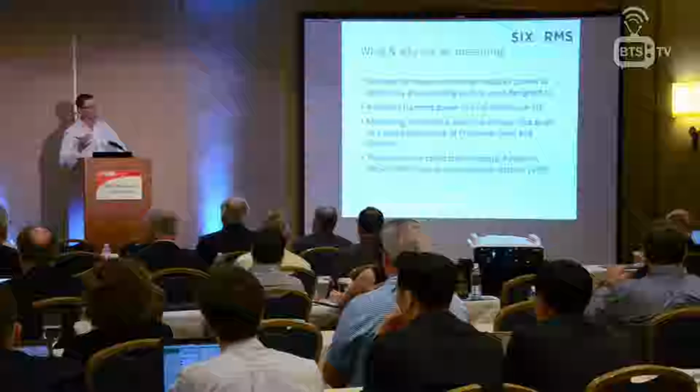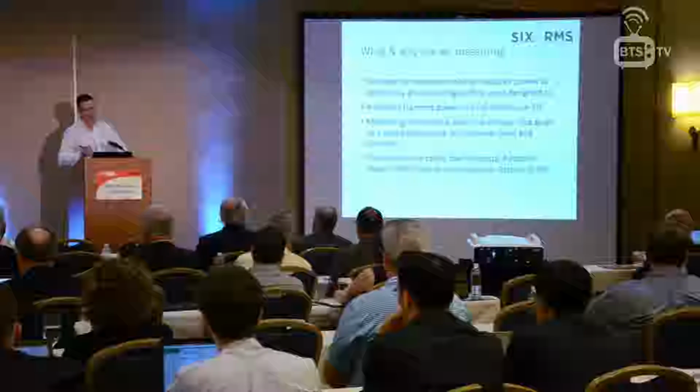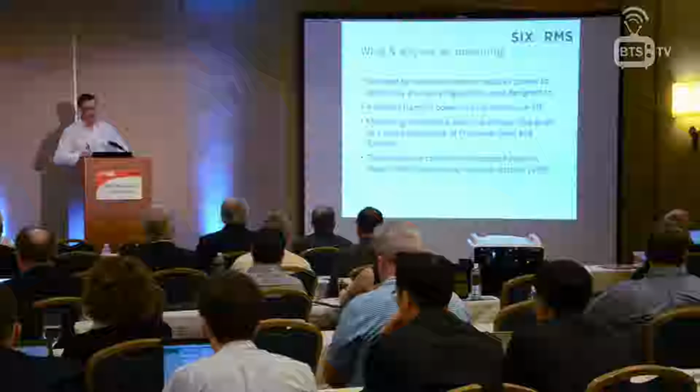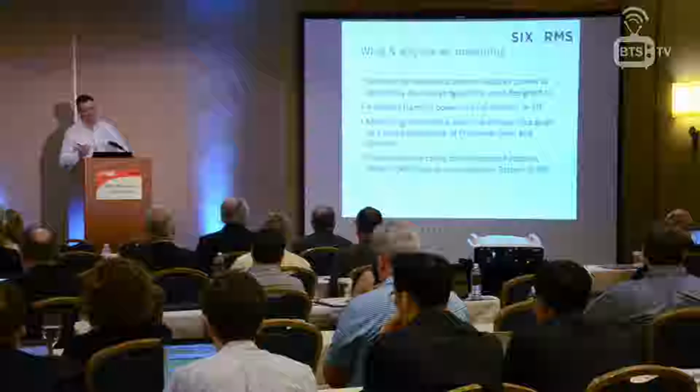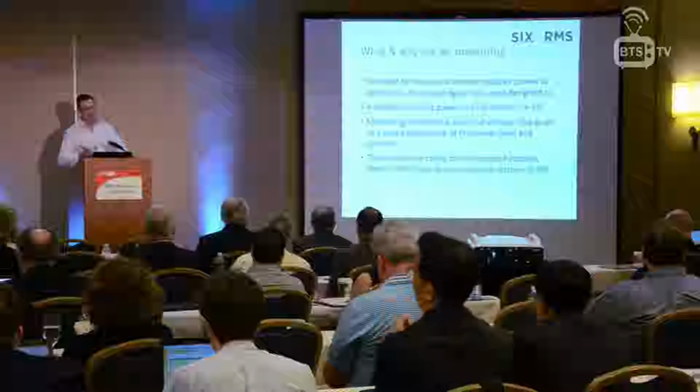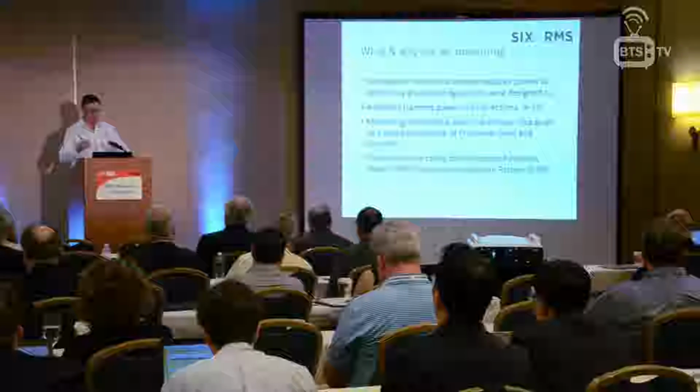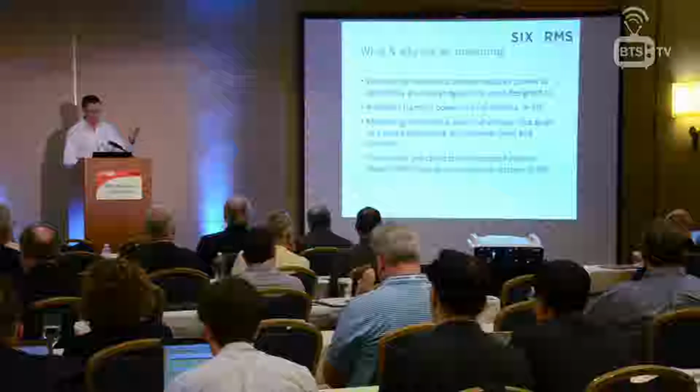We do a horizontal slice and a vertical slice, and that gives us enough information to tell us the health of the antenna system. We call the horizontal slice a horizontal radiation pattern, HRP, and the vertical slice a vertical radiation pattern, or VRP. I'll use those phrases throughout this.